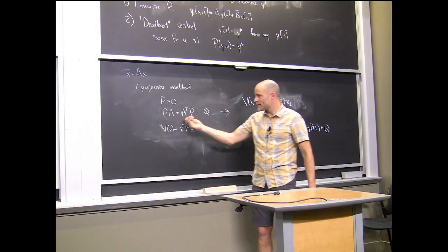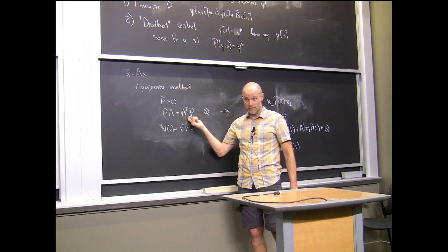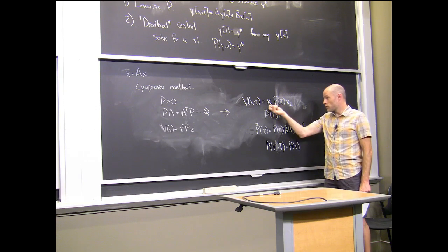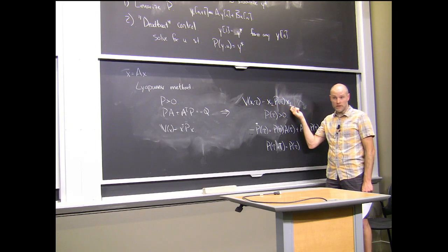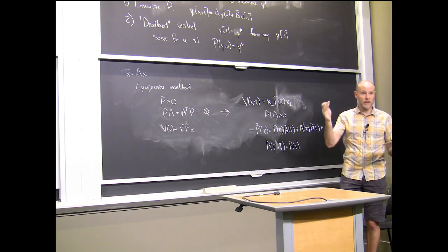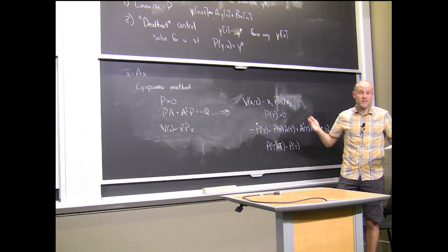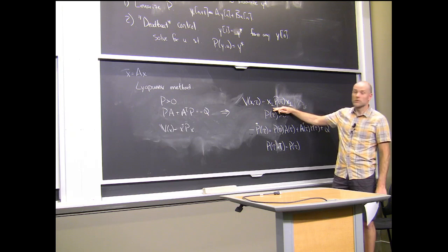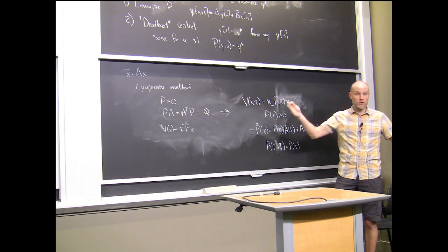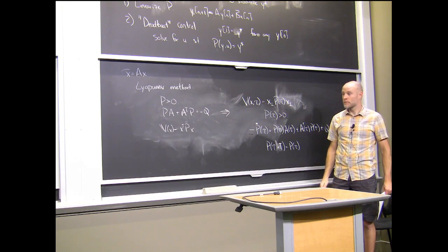We had natural methods just using linear dynamics to come up with quadratic Lyapunov functions. And they extend to the time-varying case, and we're going to use them just on the perpendicular coordinates. And we get our beautiful quadratic bowls around an arbitrary limit cycle. And that gives us an initial guess. And then from there, you can do sums of squares, for instance, along the cycle to try to estimate the region of attraction of the limit cycle. It's pretty good.